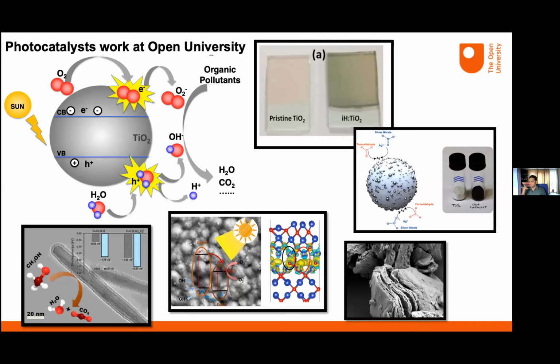On the catalyst surfaces, the photo-generated electron hole pair will start to react with the dissolved oxygen in the water and the dyes to oxidize these organic components at the proximity of the photocatalytic surfaces, and this directly oxidizes the adsorbed species. The rate limiting step in this particular case is the O2 molecules forming superoxide radicals. So these superoxide radicals act as effective agents in the dye reduction.